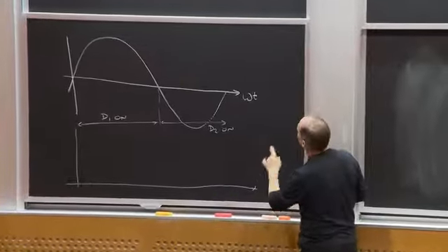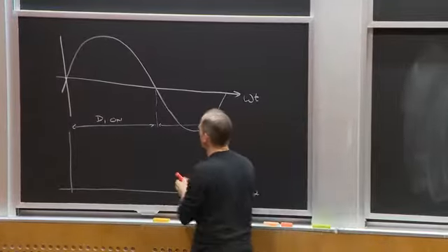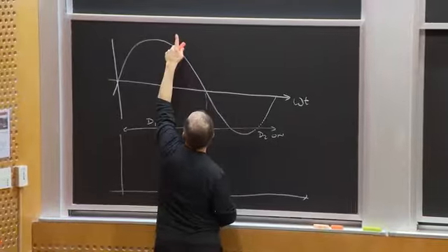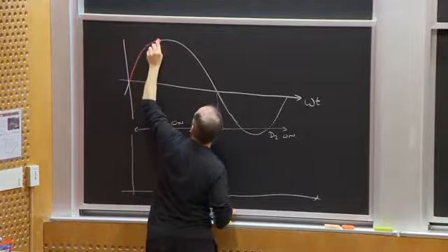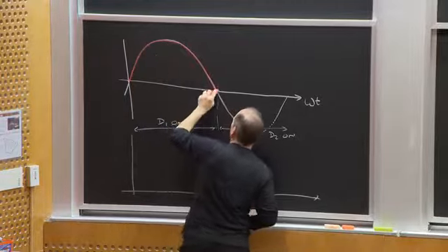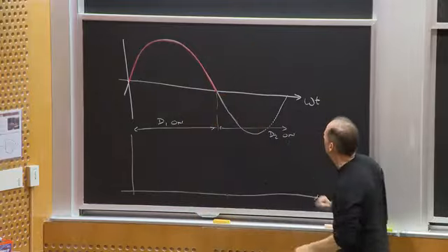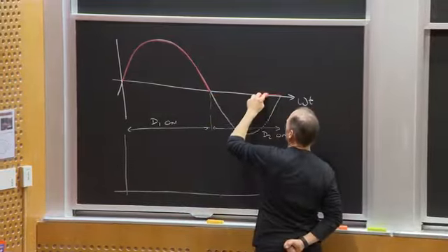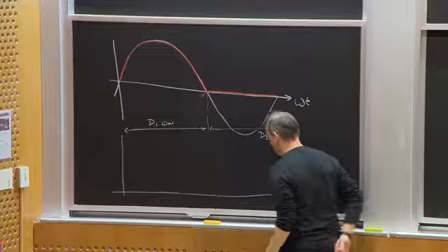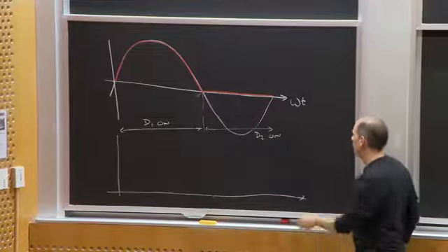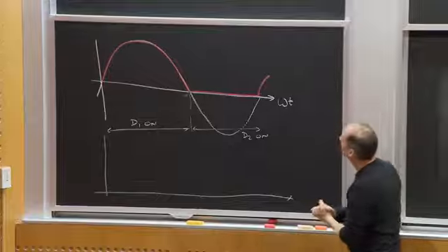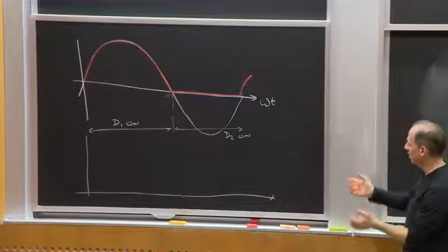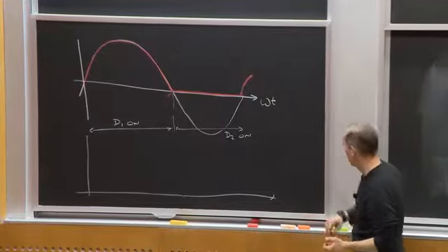So that meant that our voltage Vx looked like this. In the positive part of the cycle, when D1's on, basically it just tracks the input voltage. And in the negative half of the cycle, I get 0 because D2's on, okay? And this just repeats, okay?